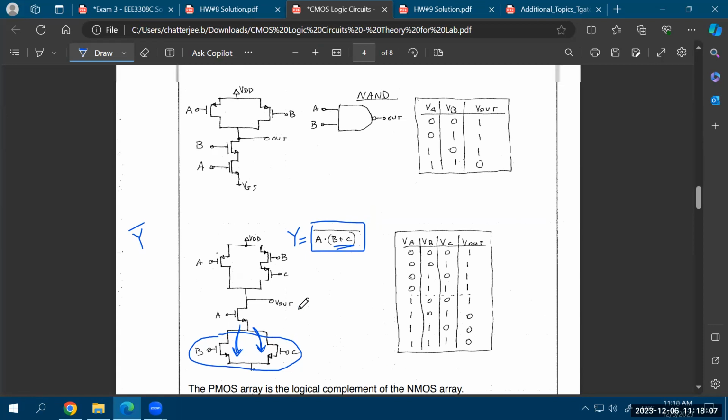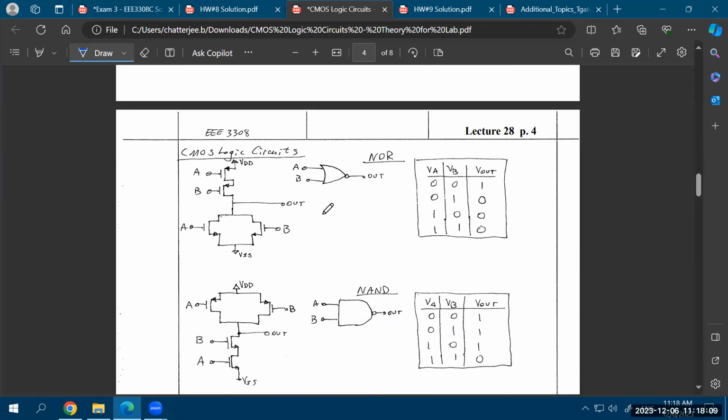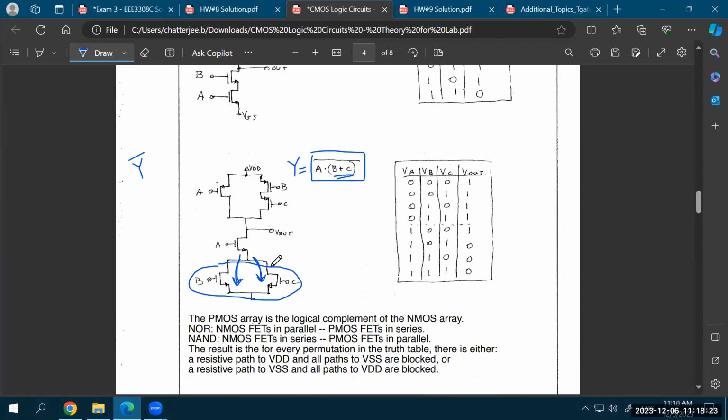So if you needed to represent a full OR gate, consider how many. For example, a NOR gate takes 1, 2, 3, 4, and then you also need to place an inverter over here to make it OR. So an OR gate will need 6 transistors. Correct? Here you are representing the OR function with 2 transistors, instead of drawing the OR gate. You are just representing it with the transistors.